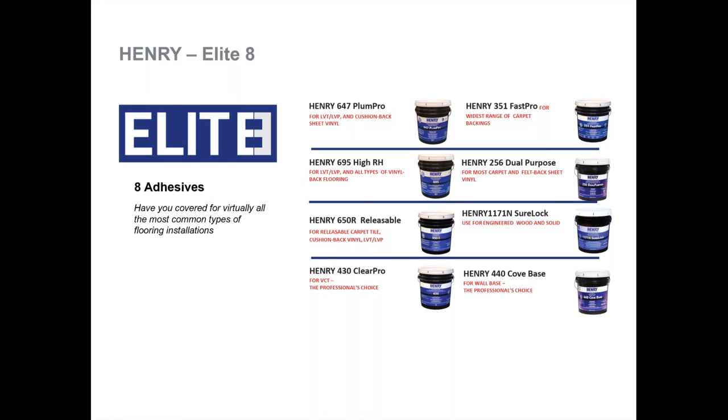But these are our Elite 8, as we call them, adhesives that we have out there. 440, a cove-base adhesive, has been the industry standard for many, many years. We have an acrylic urethane wood adhesive, waterborne but very high solids, nearly 90% solids, very easy to work with, 1171.